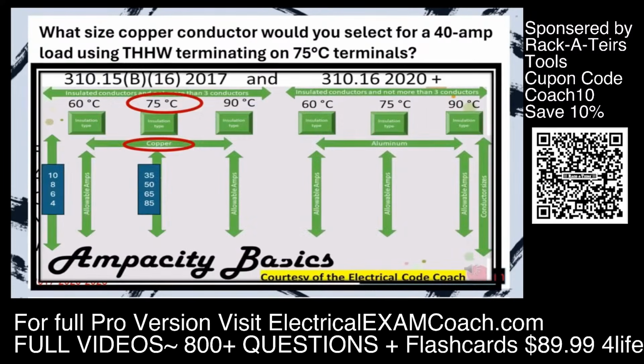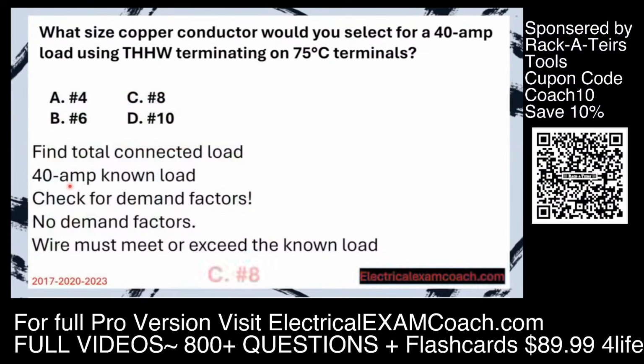We head to our primary ampacity table, and the first thing we're going to do is check the type of conductor. It's copper, so we're going to start on the left-hand side of the table. We're in the 75°C column because that's our terminal rating. Then we're going to slide down and find a wire that meets or exceeds the known load, and we find out that it's an 8-gauge conductor. And we select C. Great job.